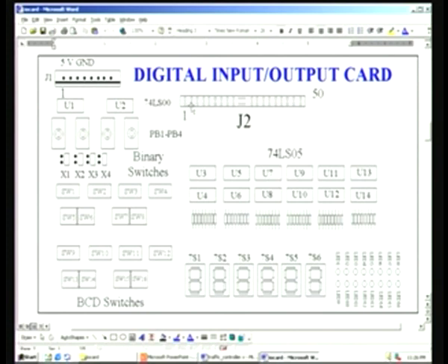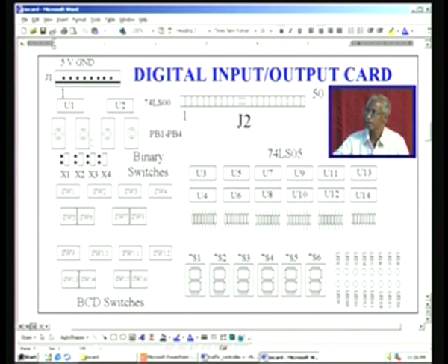So this is the point which we will have to connect, and second push button is connected to pin number 4, and pin number 5, pin number 6 respectively for PB3 and PB4. And in this fashion, all these switches, you see some more switches here, all of them are connected in the very same order, left to right, like a raster scan order you can say.